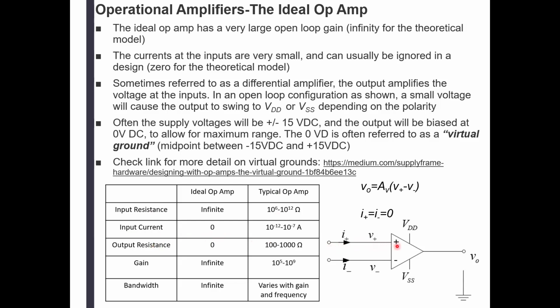So this current here, why do we have an arrow here? There's going to be other parts connected to it, so the current is going to flow through those parts around it, but not into the amplifier, not out of the amplifier. So that makes a pretty good buffer too. If you want to isolate two pieces of equipment or two stages of a circuit, then that's a pretty good thing to use. You can have a unity gain amplifier, so you have 1 volt on the input and 1 volt on the output. So why bother using the thing? Well, the reason for using that is if you want to isolate electrically that part of the circuit and maybe that part of the circuit as well.